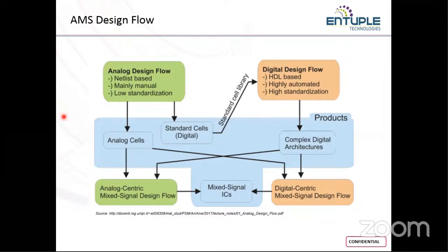You have to do it manually in order to enhance the quality of the particular layout. So the analog design flow is what we call full custom, because it is very critical and time consuming, but the designer has an idea of what might be the errors and how to clear those things off.